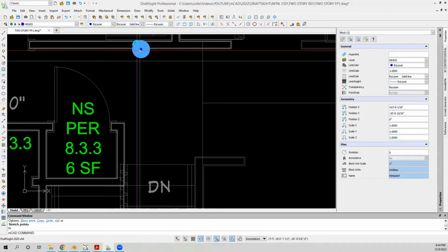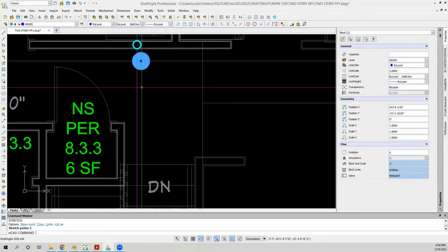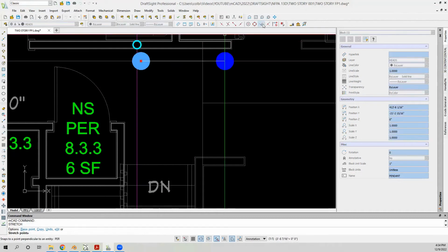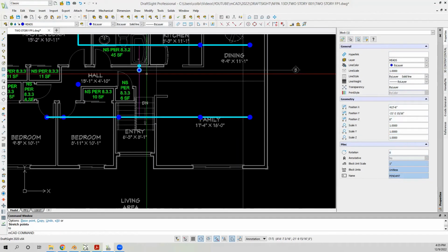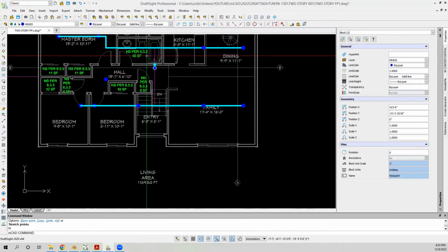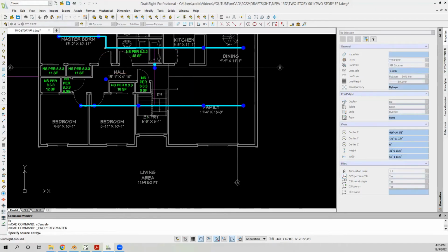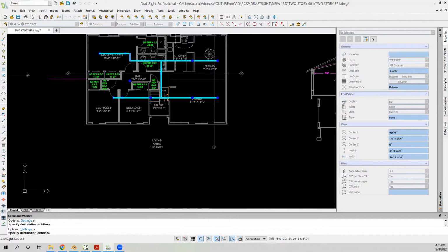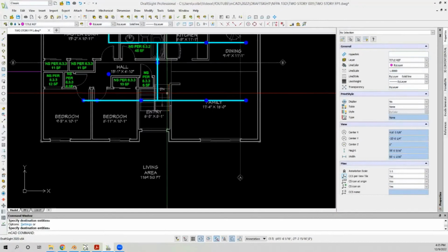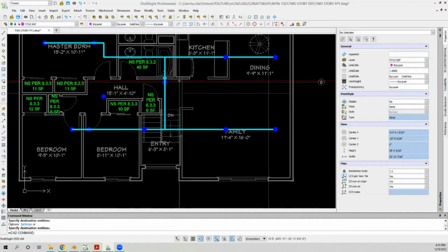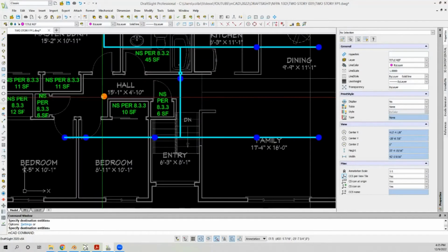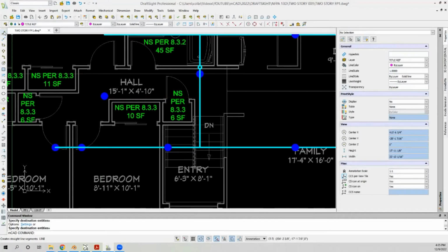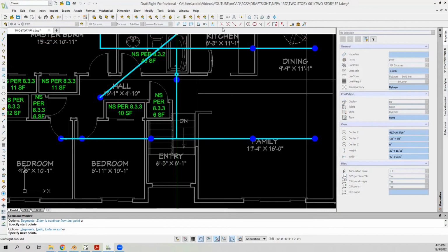Just going to move it to here, and 6 inches from this wall, and then just onto that line. Let's go ahead and do match properties, make this into pipe. We were connected to below from above, and we just need to connect this head. I'm going to change to my pipe layer, so I don't have to keep using match properties.